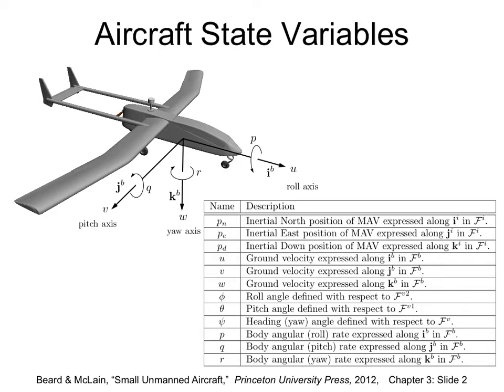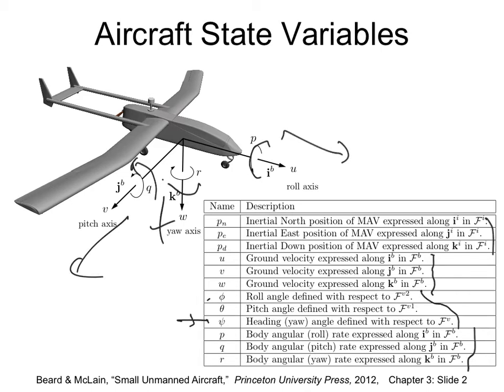And it's written there. If you see FB, IB here, and if you see body frames here, you'll see that body, inertial, and phi, theta, psi are all defined in 3 different frames. If you see vehicle frame, vehicle 1 frame, vehicle 2 frame. So phi is defined in vehicle 2 frame, theta is defined in vehicle 1 frame, and psi is defined with respect to the north, meaning the vehicle frame. So intermediate frames. And if you see the picture there, P is along this axis, Q along this axis, and R along this axis. And of course forward velocity is U, V, and vertical velocity W.